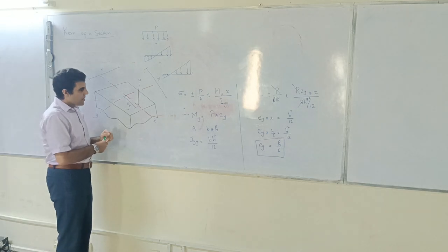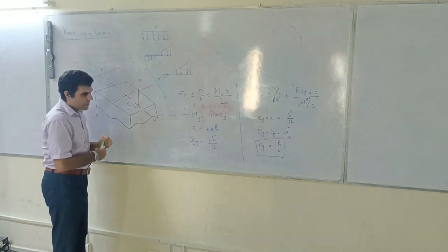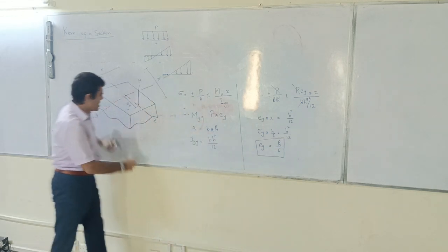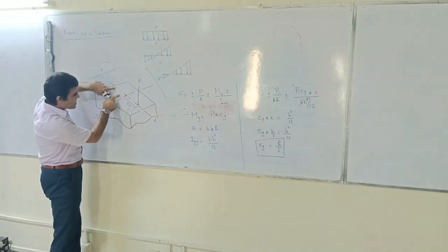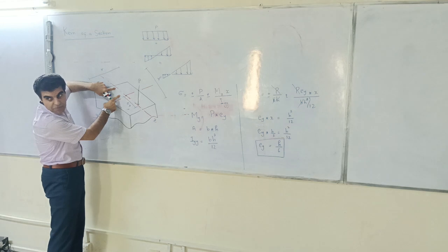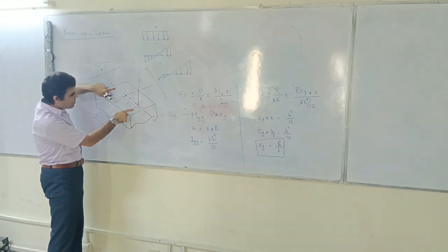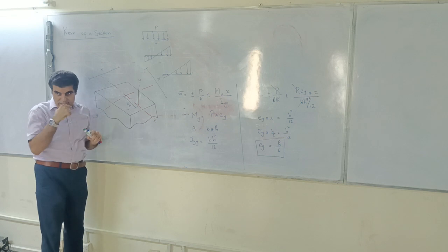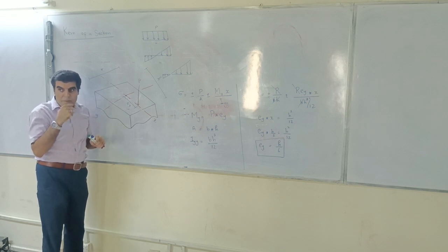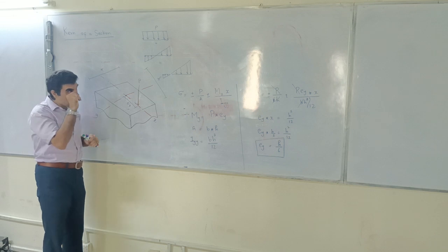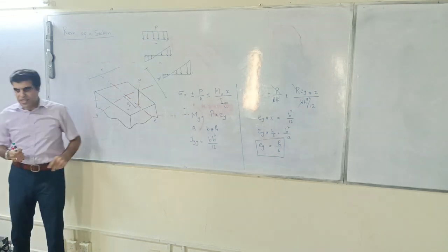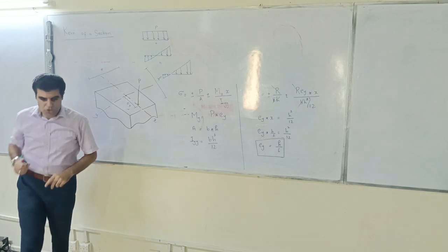If I place my load within, this E_y and this E_y, both of them should be H by 6. So if I put this load within H by 3 in total, in other words from the centroid, I will always get compression, and that is called the kern of a section. We'll discuss this further in the next class.